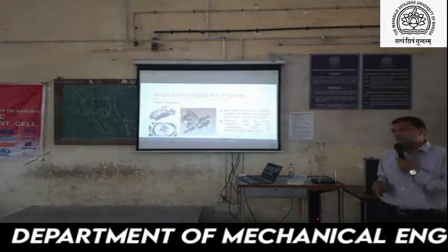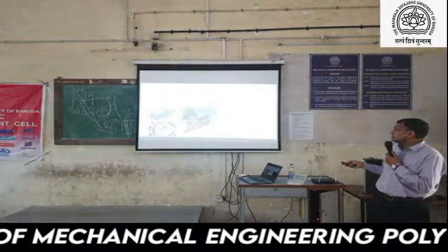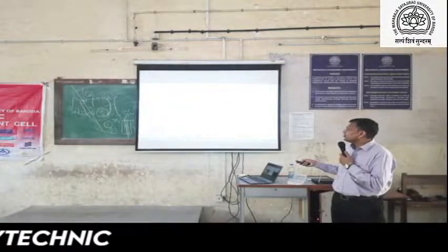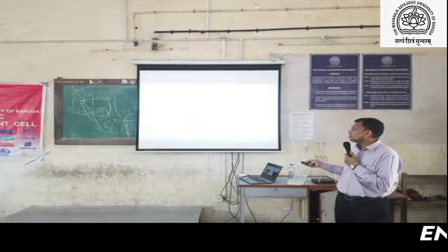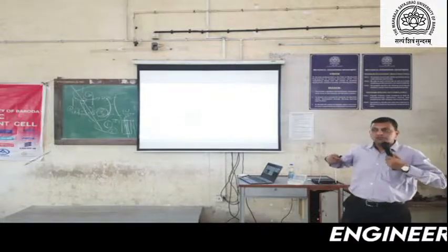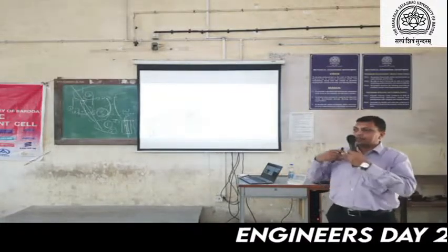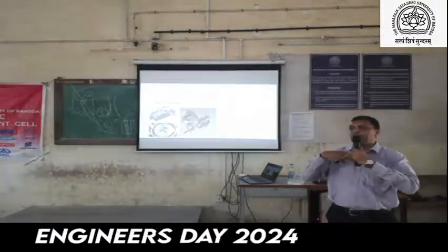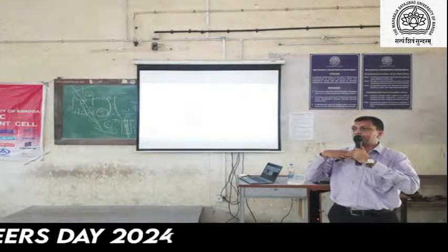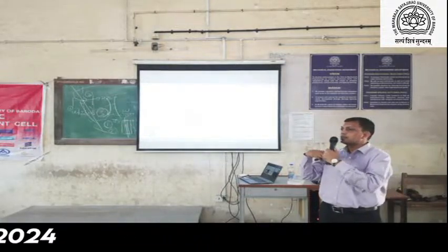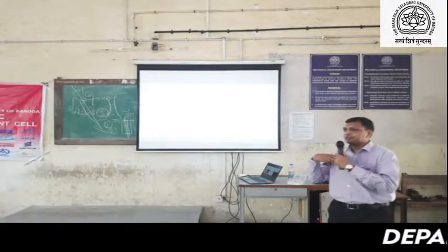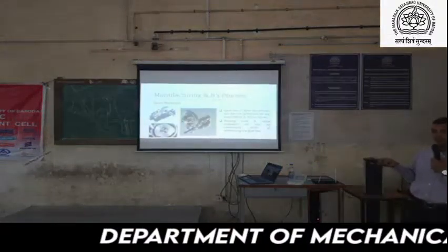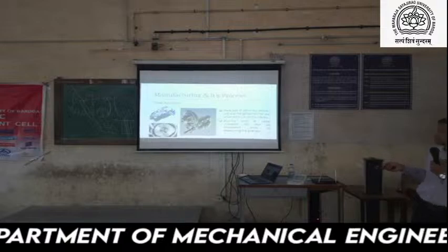If we consider this is a taper roller bearing and we fit the two covers together only, then the bearing comes in full contact. So if there is some clearance between them, it should be good for the application. That can be a particular value based on the loading, distance and all the things.